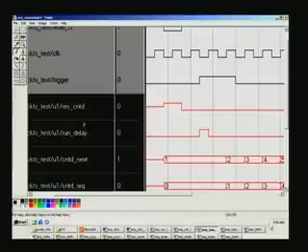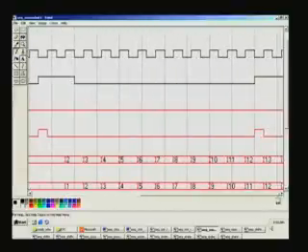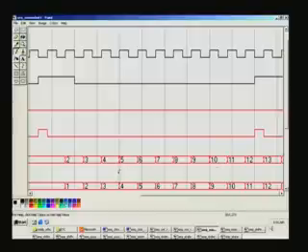And next we see here run delay is rising, and here also somewhere when the counter is 12. The reason is I purposely triggered it once again when the counter was already running, just to demonstrate that this is non-retriggable. So it does not reset here, it merely ignores.